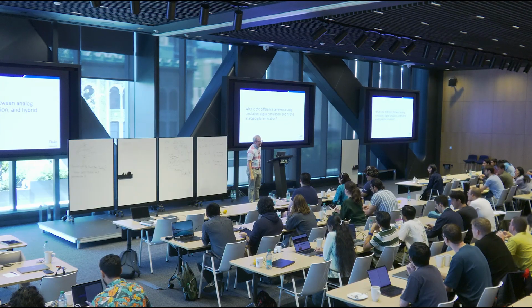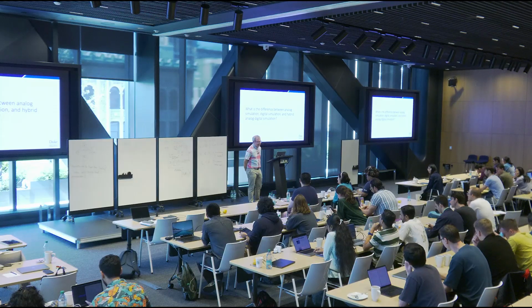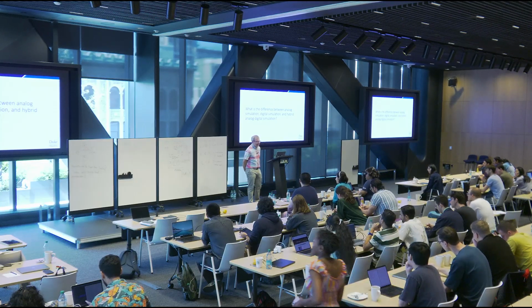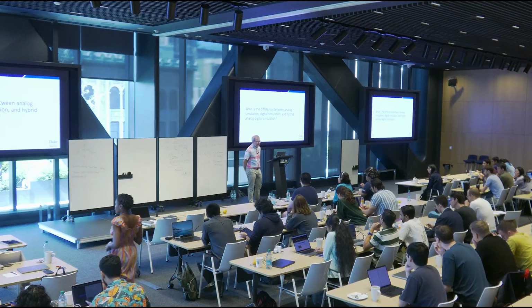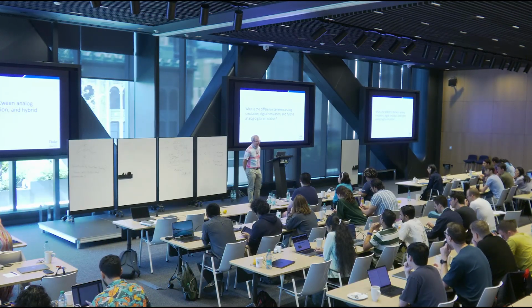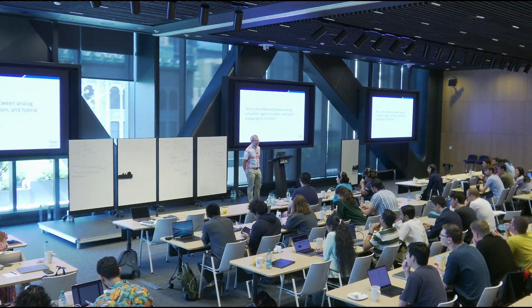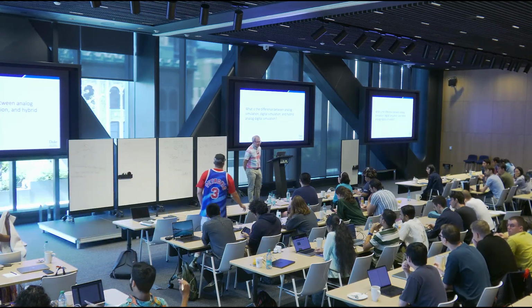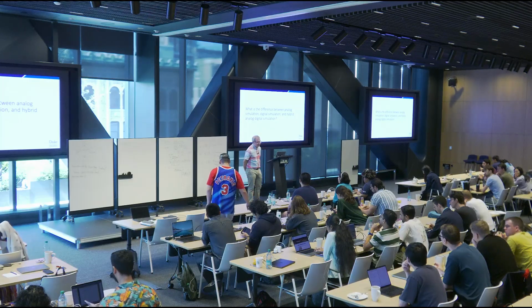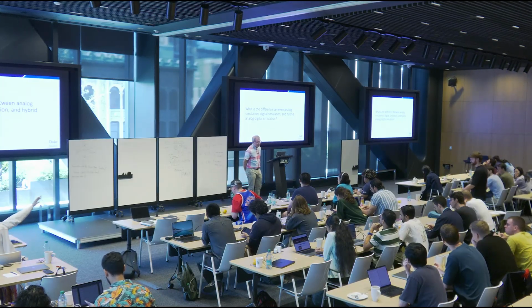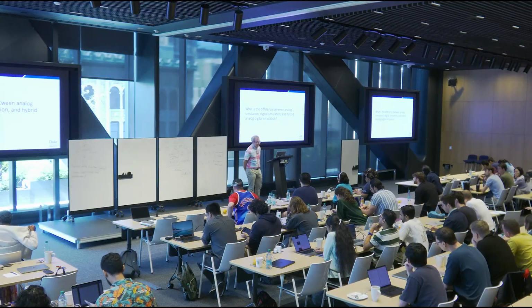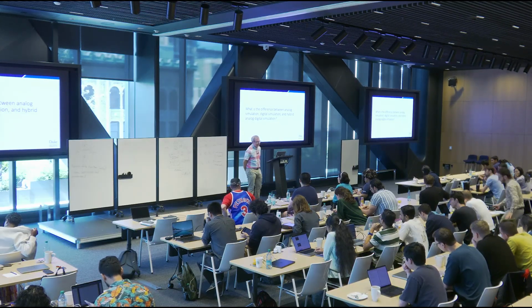Actually digital, because we have a bound for the voltage that can be between 0 and 5. And then there's a threshold of, let's say, 2.3: if the signal is below 2.3 volts, it's 0; if it's above, it's 1. The difference is that in digital simulation you have a digital bound, 0 volts and 5 volts, and you correct it every step.